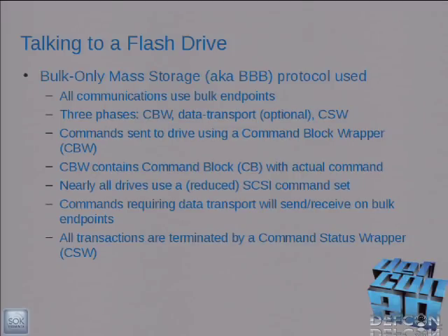There's a command block wrapper phase, where you send a command block in a wrapper, data transport, depending on the command, and then a command status wrapper where you say, hey, did this succeed or not? All right, so most of these drives use a reduced SCSI instruction set, and if you have to send or receive data, you use a bulk endpoint for that.